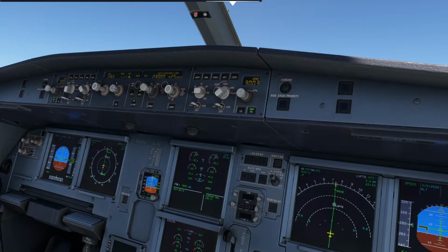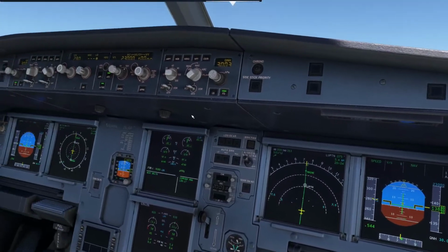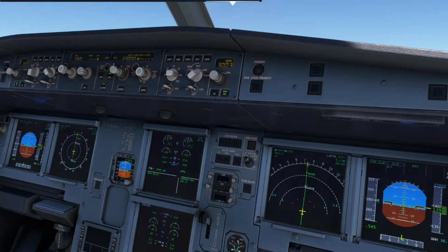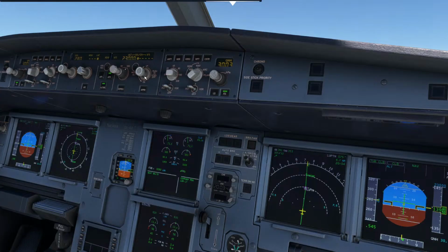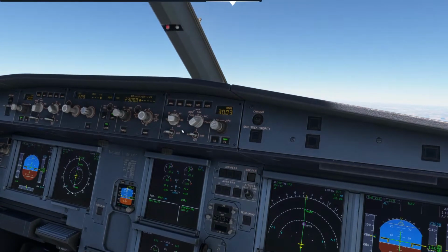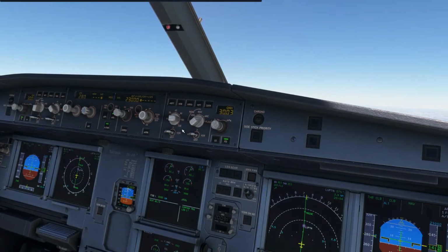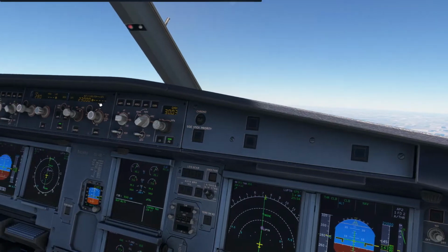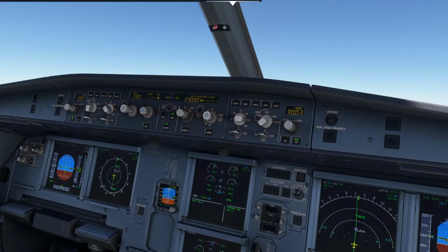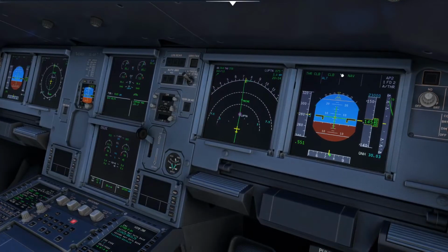So I'm going to go back to managed climb. Oh no, I got to hit the altitude one. So you push on the altitude window to go to managed climb. If you push on the vertical speed button inwards, it'll level off. That's what it does. If you push in on the vertical speed knob, it levels off. It doesn't go to managed. You have to push the altitude knob to go to managed. And now it says climb again. 280 knots.